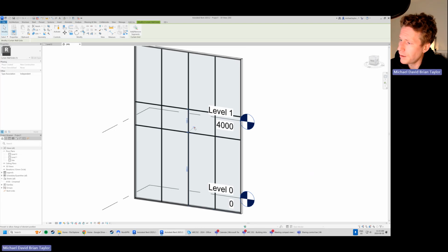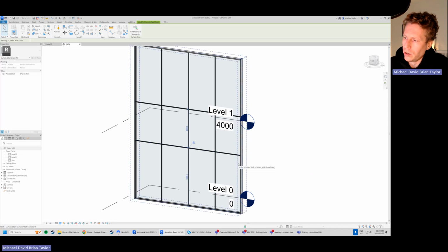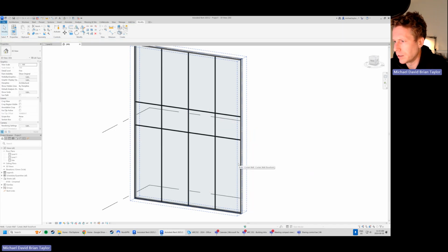You might want to repin it. So if we wanted to repin this, so what happened? When I repin it, it's saying to Revit that we want to go back to the type parameters, which we set up previously. So for now, what we can do is let's just undo that, leave it unpinned, and that will give us the flexibility that we need to make some modifications.